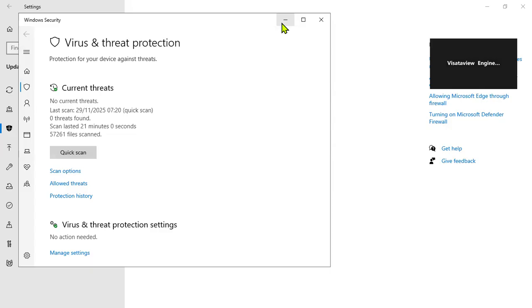Okay. Now, let me come to your question. Some of the GPS will give you the RINEX straight. They have incorporated the converter inside already. So you can just download the RINEX data directly. When you get the RINEX data, you don't have to go through the raw data process, converting it to RINEX again. So you can just go straight to the Magnet tools and process it there. Please, do you get it?